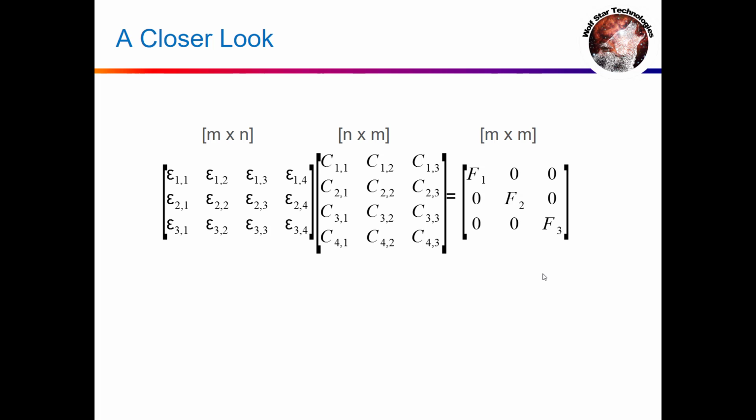So if we had a cover and we solve that cover for its normal modes, and the cover is attached to the structure, if we put unit displacements, XYZ unit displacements, at the attachment locations, and we laid strain gauges with TrueLoad based on all of that, so the unit displacements plus the mode shapes, and we collected the strain data and brought it back through TrueLoad, it would essentially be doing a Craig-Bampton analysis. We get the ground flexibility going into the structure through the unit displacements and the harmonic response with the mode shapes. So it's an extremely powerful way to understand the dynamics of your structures.